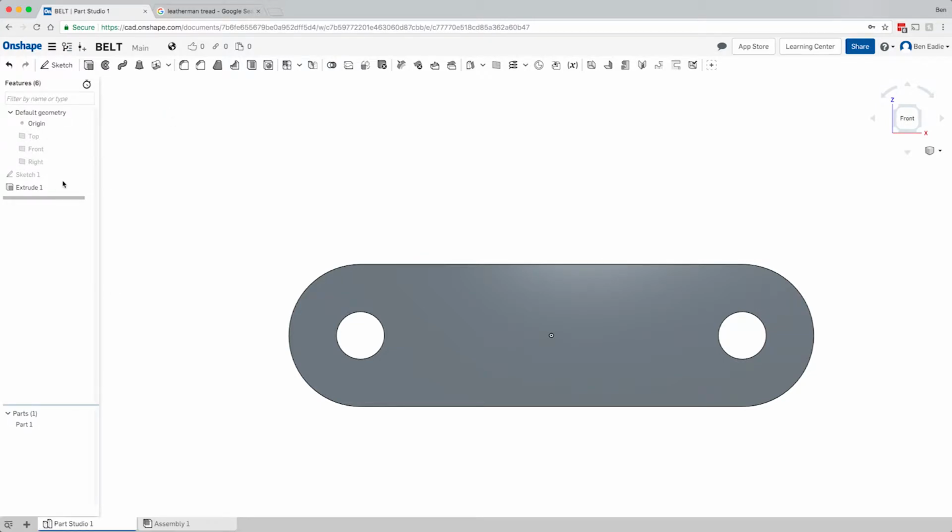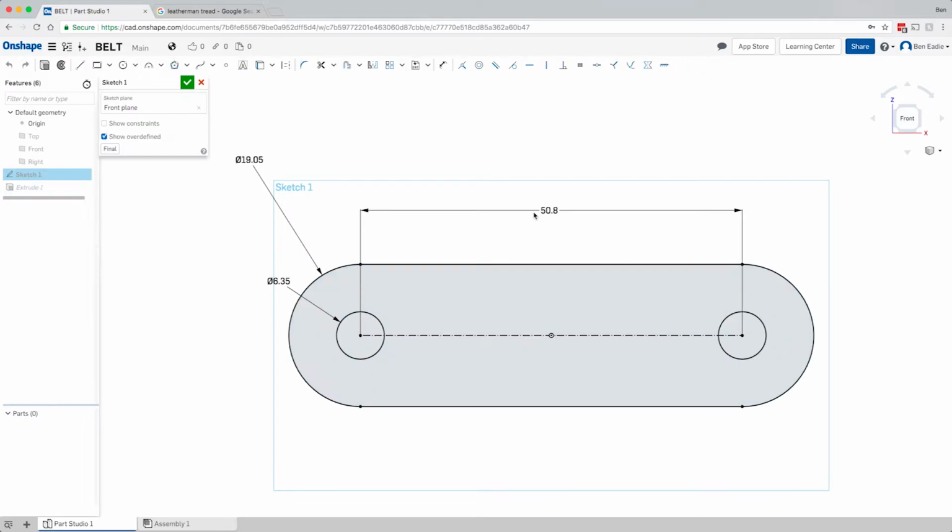And you notice that it shot us outside of the sketch again. And that can be a little frustrating, but once in a while you kind of just have to deal with things. So we're going to right click on it. We're going to hit edit. And now we can see that we have these dimensions here. The dimension for the diameter of this hole here is, you can see from earlier before, we put in 0.25 inches, and you can see in the dialog here that it says 0.25 inches because that is what we put in. But when we select outside of it, you'll see that it converts it to millimeters.